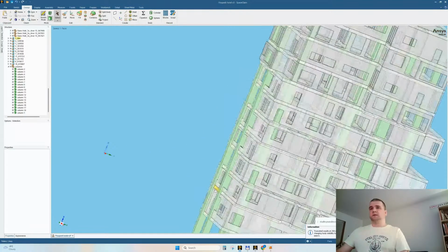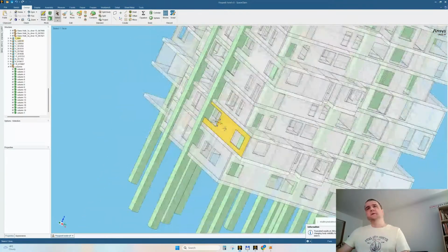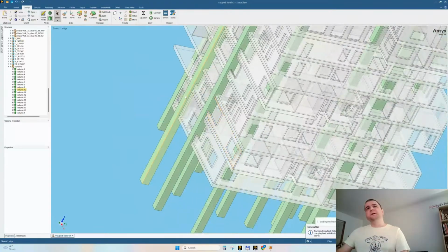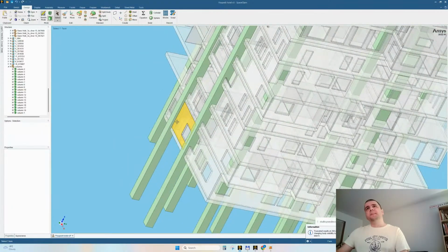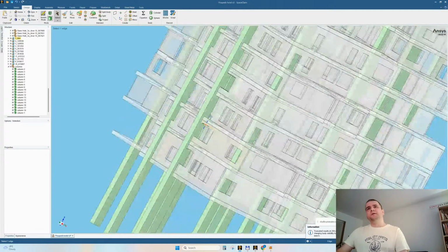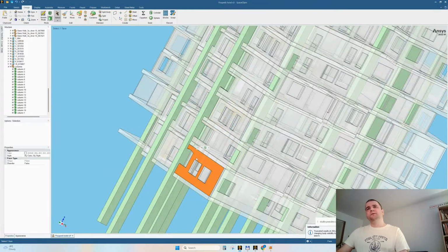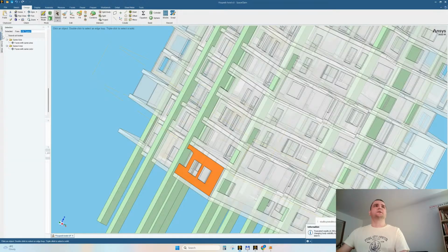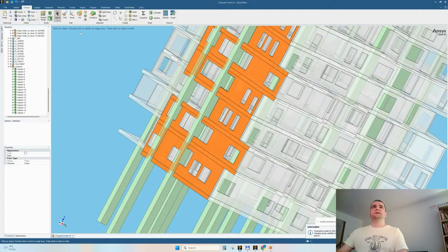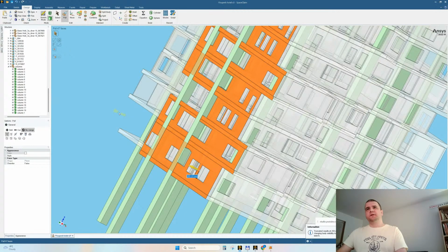Yes, the columns are pretty much sticking out, you know. So how do we solve this? I am going to select these faces, for example, search about this coincident face. I will select these faces, pull, no merge, and I'll pull until it's even, let's drag and drop, you know. So these will be very thick walls.